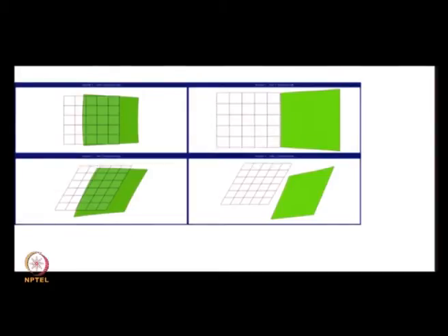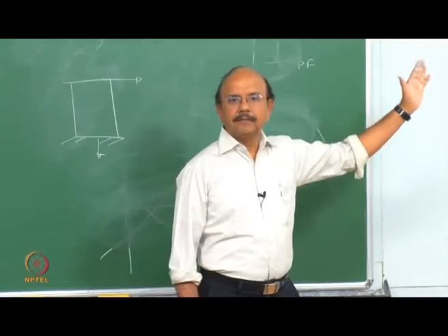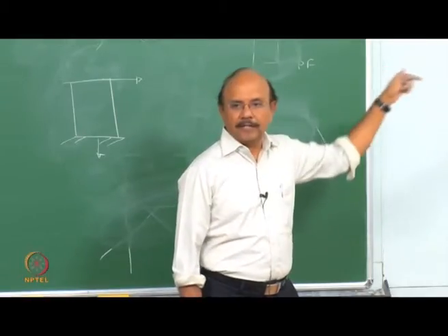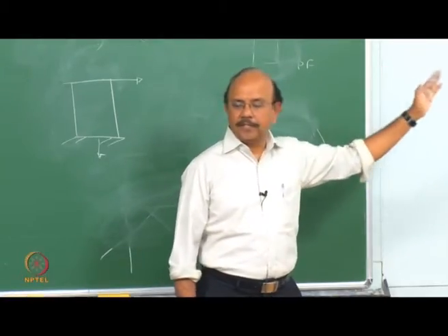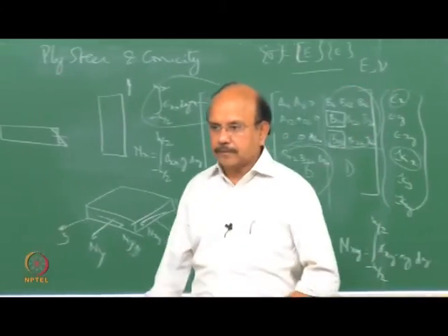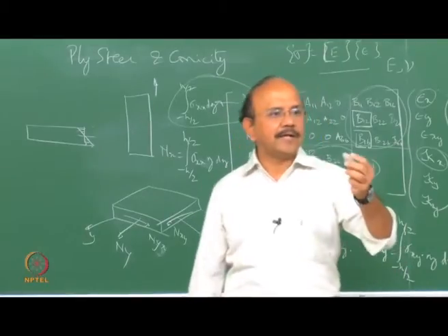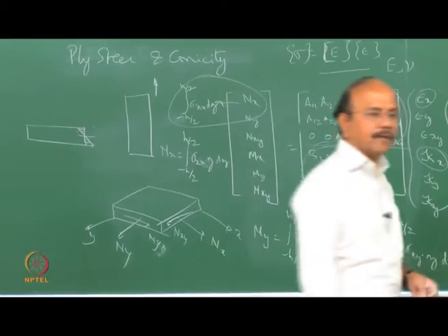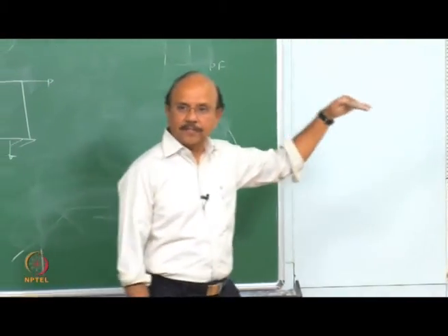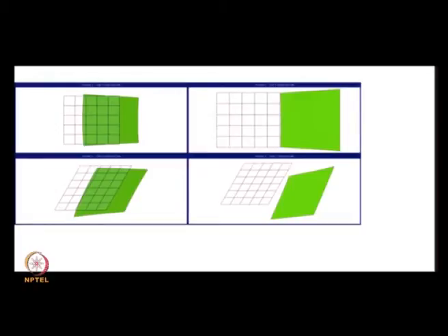It shows that when I apply a force F, let me call that Fx, the displacement is only in the x direction. For that rhombus, which is very similar to the tread block, if I apply a force Fx, there is also a displacement in the other direction, y. You can see that in the bottom picture.